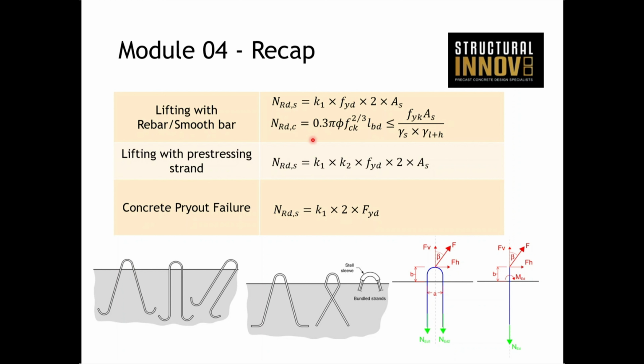Your concrete check was an anchorage check formula, and I had a couple of slides on how this formula was derived, and it had certain assumptions within it. But it all stems from chapter 8 of Eurocode 2, how to calculate the anchorage length of a bar. Also, when you calculate the anchorage length, your strength still must be less than or equal to the actual strength of the bar. So you don't gain anything from adding more than what's required in terms of the anchorage length.